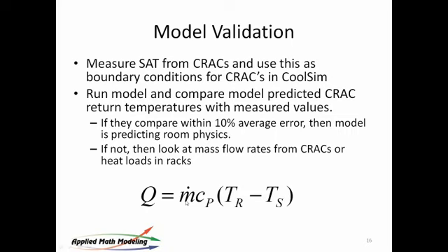And that's common too for older units, because the filters get dirty, or something happens that degrades their performance. And so we've seen people doing measurements in the field tell us that in fact the rated mass flow rates are not always what they are, or the measured mass flow rates are not always what the published values are, depending on the age of the unit.